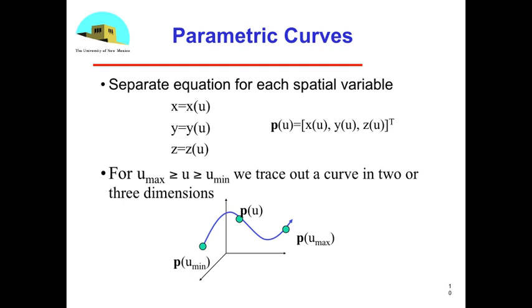If you're working with homogeneous coordinates, we'll at times want to put in a w of u, and we'll see that in a lecture or two, when we talk about NURBS curves and surfaces, where you can actually have the w value also defined by a parametric equation, and you'll go back to xyz space by doing a perspective division, dividing by w.